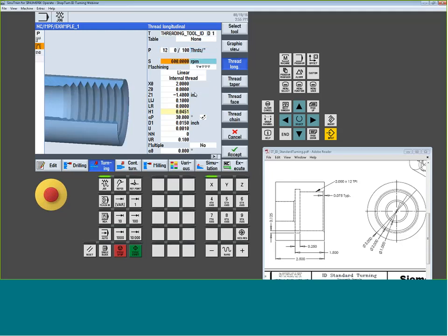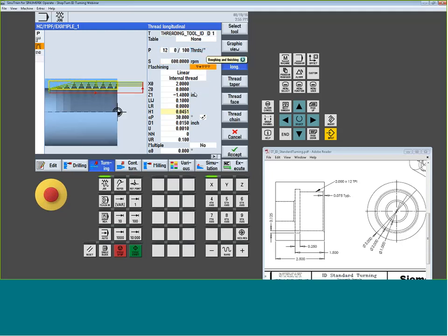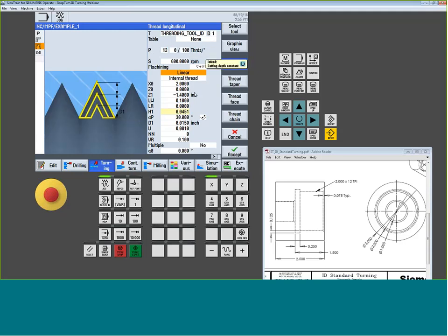Okay. Some RPM. What's my strategy? Roughing or finishing. This is all the same as we've done in other operations before. Linear or degressive. Constant depth, constant volume, right? So typically I would always want to use a degressive value, so the depth of cut would reduce as I get deeper in my engagement.